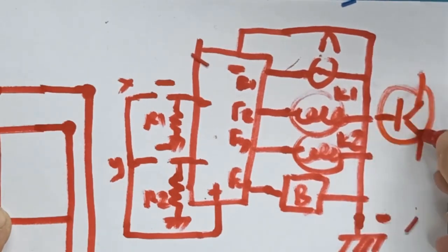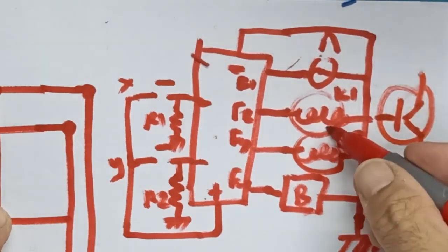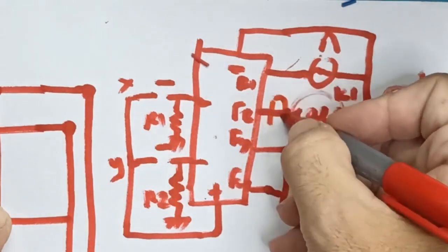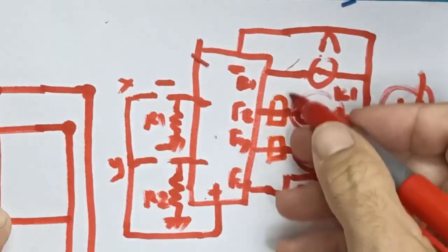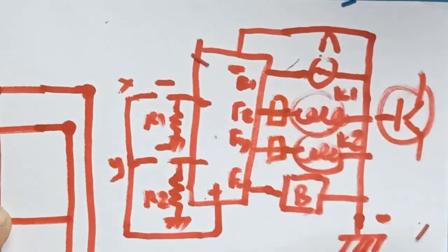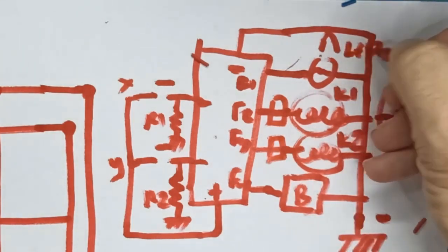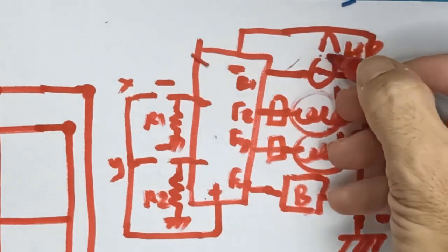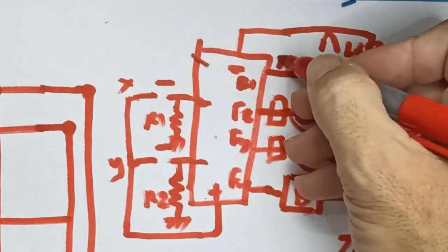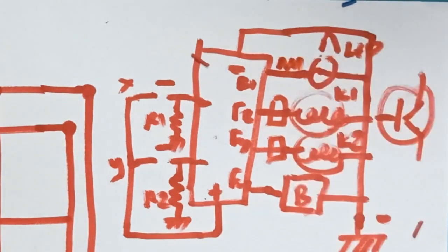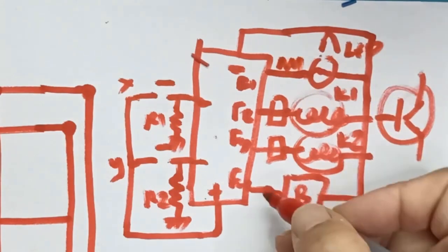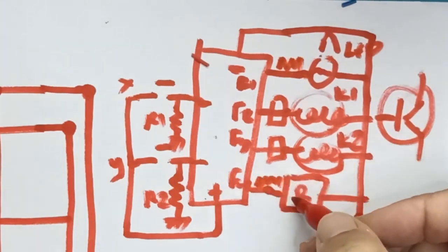I will connect them like switches, and they will drive the relays for me. Here will go the transistors. They will amplify, and lead me to the relays. And from there, these relays will lead me to the motor. Here we reach the conclusion that we need analog electronics just as much as digital ones. It is a combination of the two. I can't work with digital electronics if we don't have the analog ones.